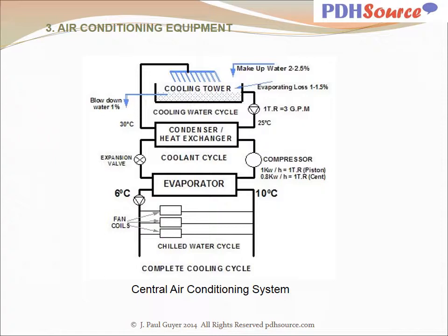The cooling tower consists of a basin at the bottom that holds water, and water is drawn out of it by a pump, and it is pumped to the condenser coil, where it cools using the water, which is at around, in this illustration, say 25 degrees centigrade, and that water is pushed across the condenser coil, and it cools the refrigerant so that the refrigerant condenses.